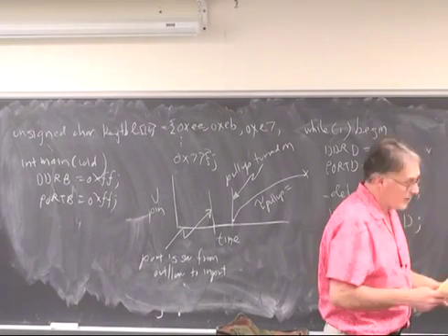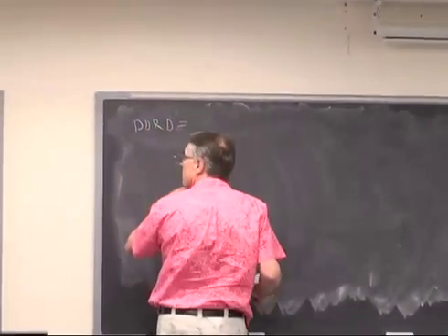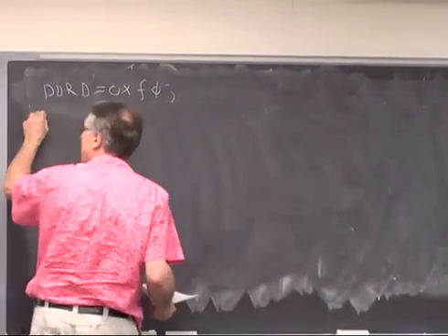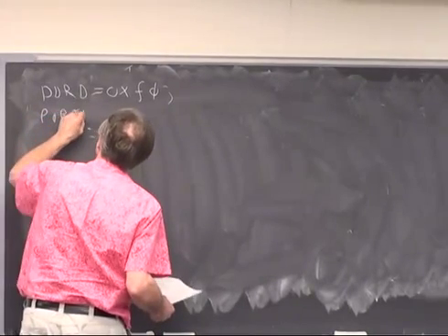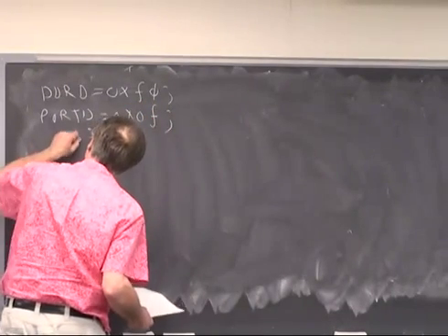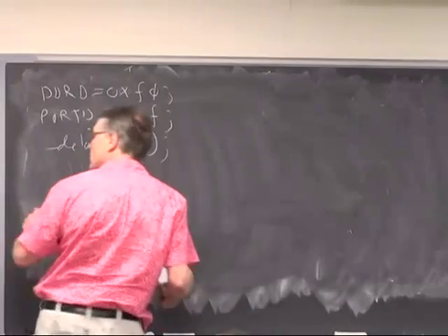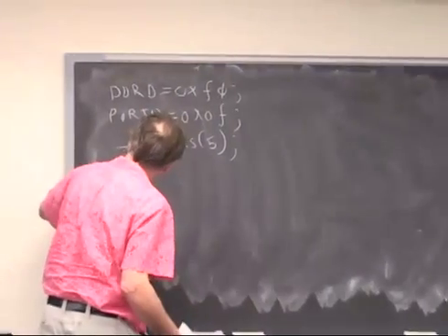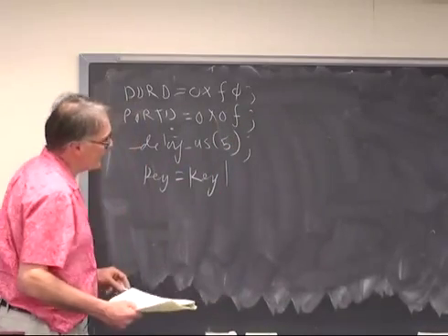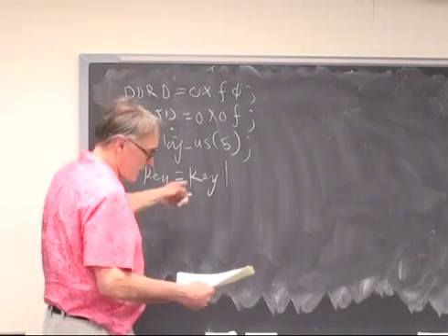Two erasers. All right, so now we're going to set DDRD to read the other direction, so it's 0xF0. And port D goes to 0x0F. We delay microseconds 5, and then read key again. Well, we're going to OR key the old value of key, which is the upper 4 bits, with the lower 4 bits,